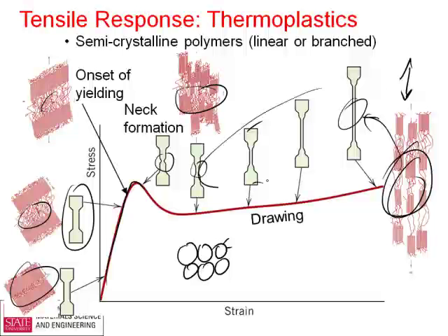You'll see exactly this kind of crazing, and you'll also see the optical properties change in this region, and that's precisely because the material is becoming highly oriented, and you can even see it get kind of more milky, and you're getting some deformation-induced crystallinity that goes on there. It's interesting stuff.